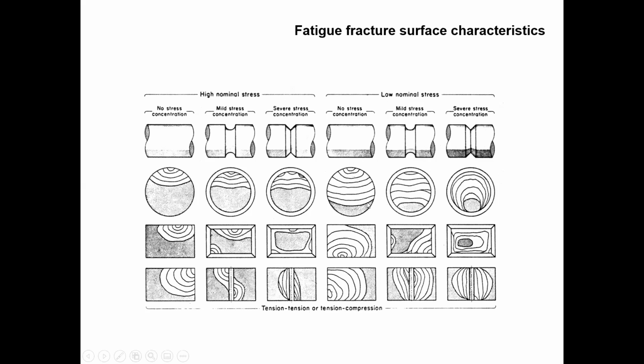So many failures are due to ductile failure. You can see the contour area is very high. But in here, if you apply an alternating stress slightly larger than the endurance limit, you can see this kind of nature, this kind of groove. This is the no stress concentration case. If you don't have a stress concentration point and stress raiser, you can see that it is highly ductile. But if you have this kind of groove, that is mild stress concentration, it is not sharp, it will be very smooth, so it doesn't have a high KT value, it's a low KT value. So this is a little bit ductile but mostly brittle.